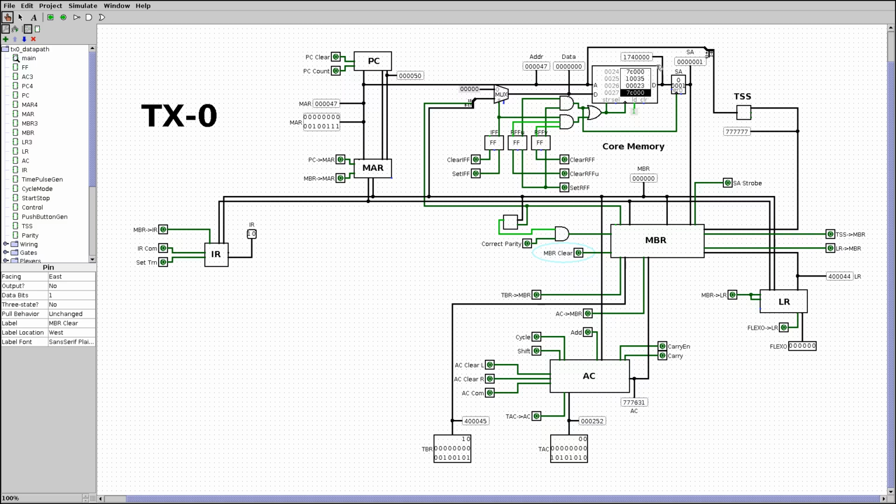Now this I had to simulate, of course, and I simulated this with a temporary register here, the sense amplifier register. So let's do this. We set the read flip-flop, and this will clear this core location and send it into the sense amplifier instead. Boom. And next we clear one of the two flip-flops, which ends the read operation.